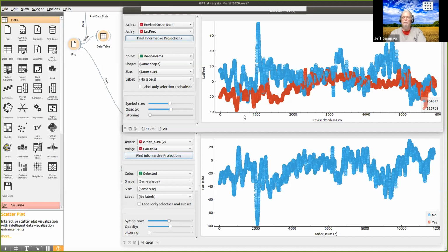It might help a little bit, but the numbers they're quoting you, that's a non-corrected GPS unit. To get the really good correction, you need to supply RTK correction data to that. So that 2.5 meters CEP, CEP is some kind of a statistical number. They'll also quote it in RMS, and I'm not sure exactly what either one of those mean, but what it really means is it's not as good as what they tell you there. So they say 2.5 meters, and sometimes it might be 3 meters or whatever. But if you want better accuracy, you're going to have to get something that's got RTK correction or some kind of fancy correction to it.